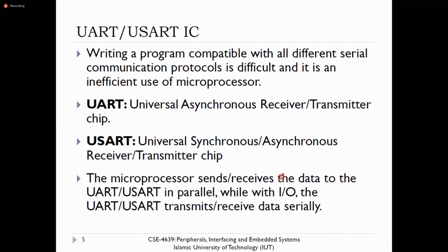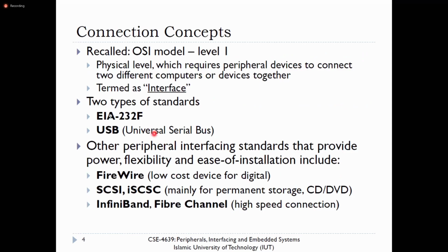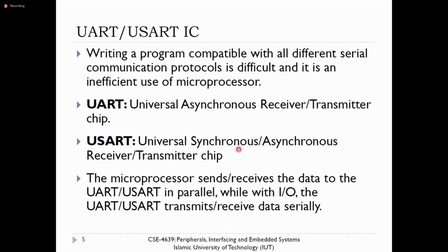So first, we'll start with the UART or USART. First of all, this is an internal interface, not an external interface, and through this we design the communication port EIA 232F. UART stands for Universal Asynchronous Receiver Transmitter, and USART is the Universal Synchronous Asynchronous Receiver Transmitter chip.